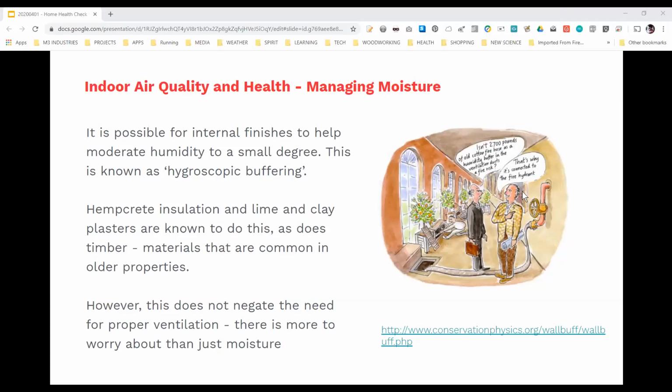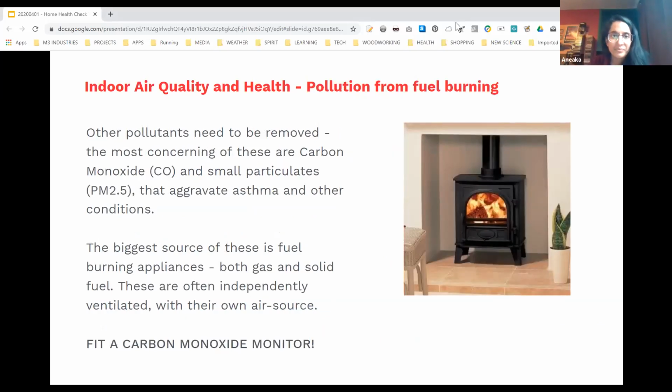You just said that if you insulate the walls, it'll keep the walls warmer, which will help. I'm thinking that you've really got to insulate every bit of the walls, otherwise you'll have some cold spots which will massively attract moisture in that circumstance, won't it? Yes, that is correct.